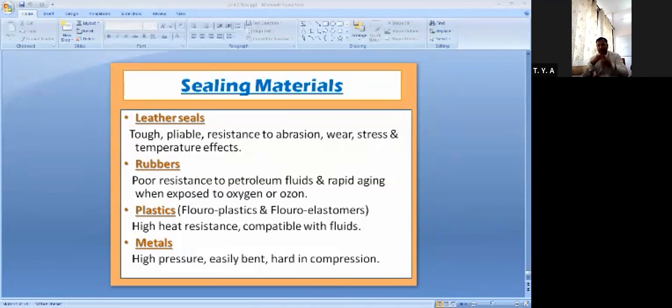In addition, copper becomes hard when it is used over a long period and is subjected to compression. Due to that also it is used. And whenever a unit or component is disassembled, the copper sealing rings should be replaced in your system. That care we have to take.